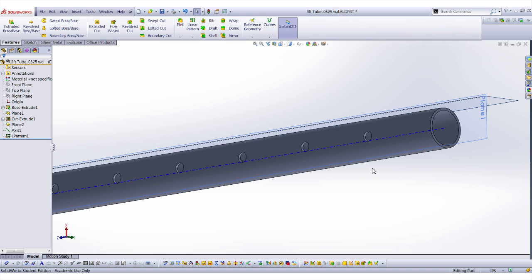Okay. So this is an error message that will come up a lot at some point in your life. Cannot rebuild feature using this sketch. There is some problem with the sketch. So most of the time, if you hit show the problem using check sketch feature, it says the sketch has both open and closed contours.